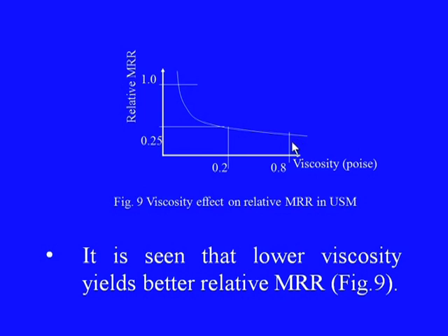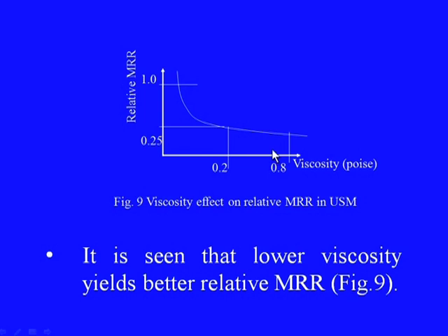As we know, the efficiency of cutting depends upon how fast these abrasive materials can hit the material in the cutting zone. Therefore, if the viscosity increases, the abrasive particles cannot move faster, neither can the debris produced inside the cutting zone be taken away faster, nor can those abrasive particles, after getting hit by the tool, move towards the workpiece faster, and therefore the material removal rate will slightly come down.